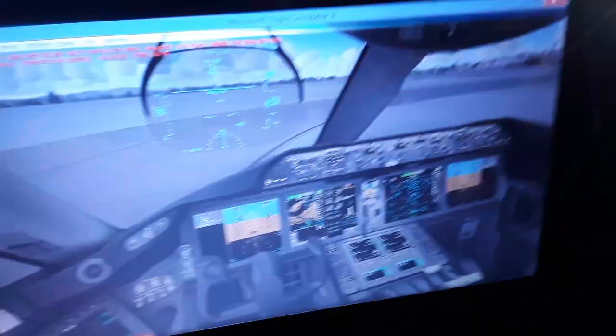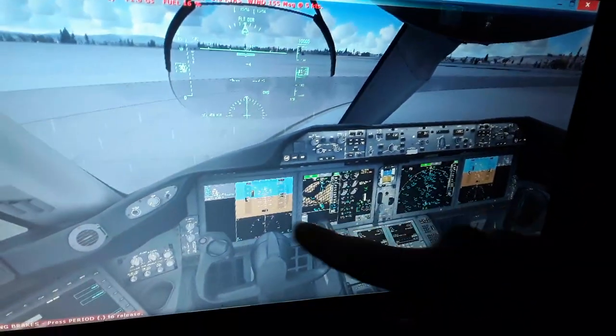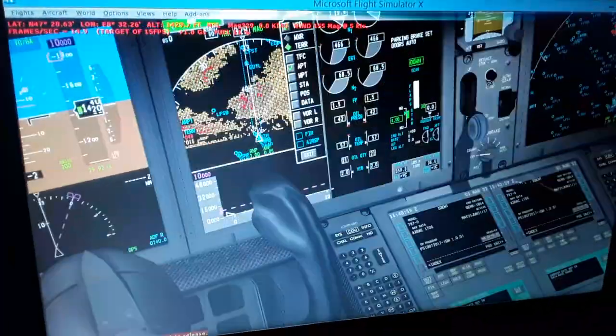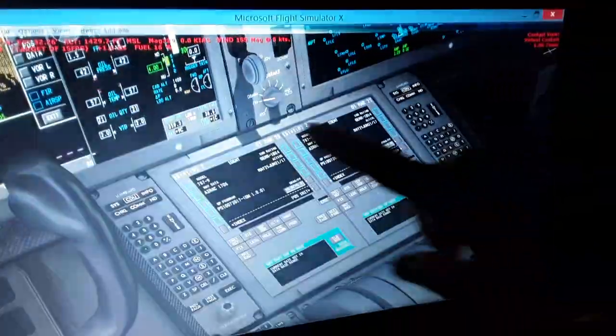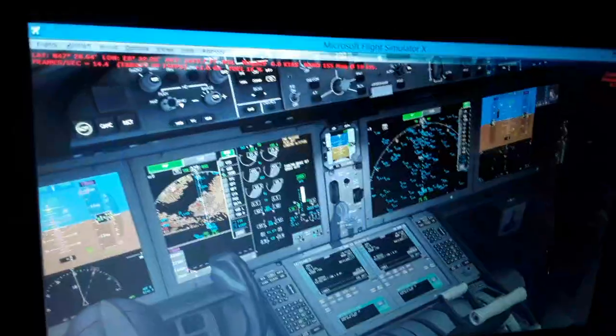You're going to see also the runway, the airport location, and the aircraft direction, location, and altitude, elevation above ground level, all displayed in the navigation display and the primary flight display. So you will see them over here. You can see the navigation display here, the horizontal and vertical primary flight display. I still have not set up the flight management computer over here. I will set through the flight management computer a flight plan or flight path or route I will use.